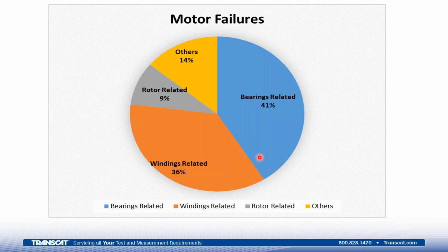Let's talk about some of the motor failures. We have bearings, which are the majority of the motor failures, followed by windings, rotors, and others, which are usually manufacturing defects and things of that sort.